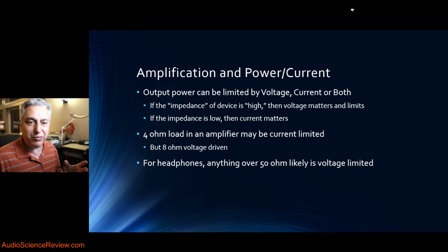So there are amplifiers you can buy where you have to provide the power supply yourself. And let's say you provide a 36 volt power supply for it, but it accepts also 48. You want to get the 48 one if your speaker impedance is 8 ohm or higher. Turns out most speakers I test are 4 ohm and lower. That means they want current. Now, that doesn't mean that they want current and no voltage, but strictly speaking, you need to have more current. So a lot of people are confused, thinking that a higher current amplifier is better for any load. It is not.